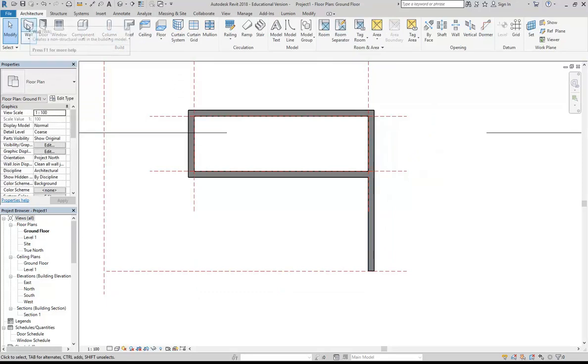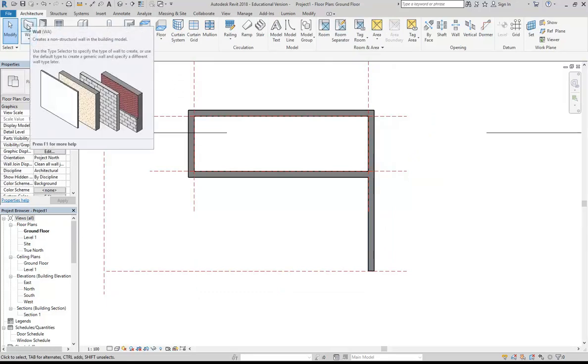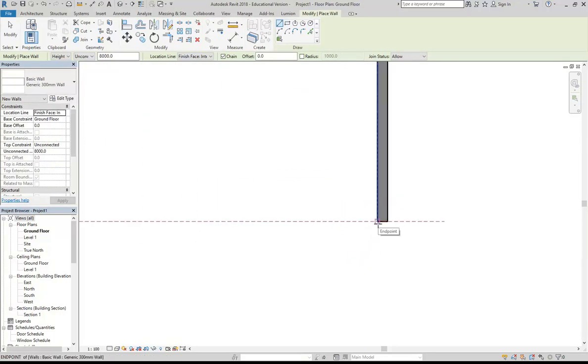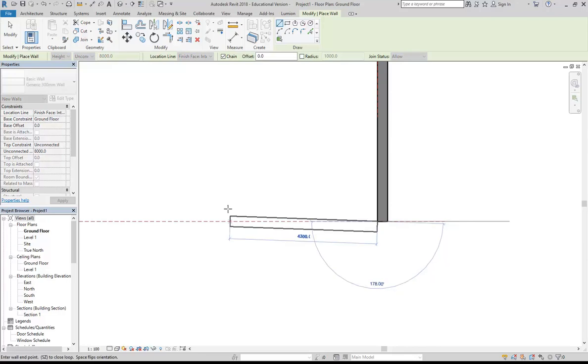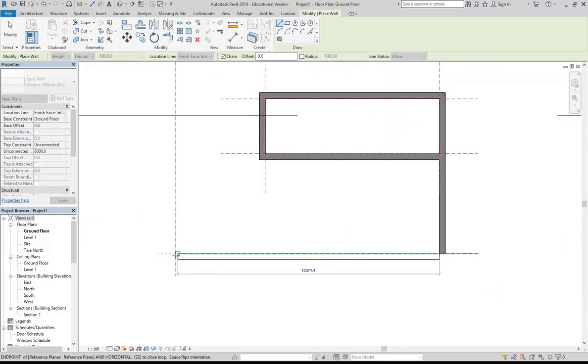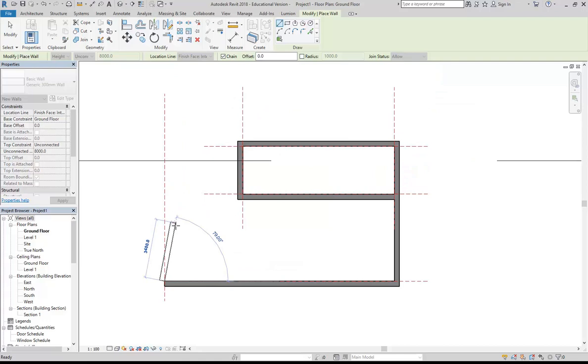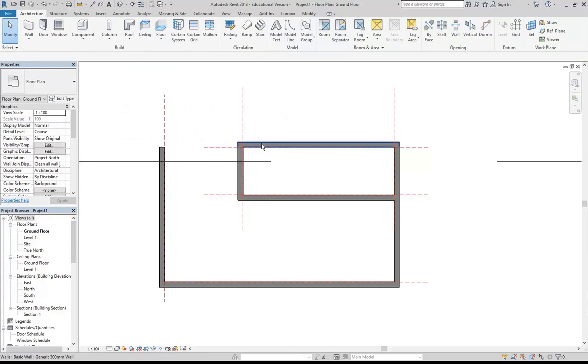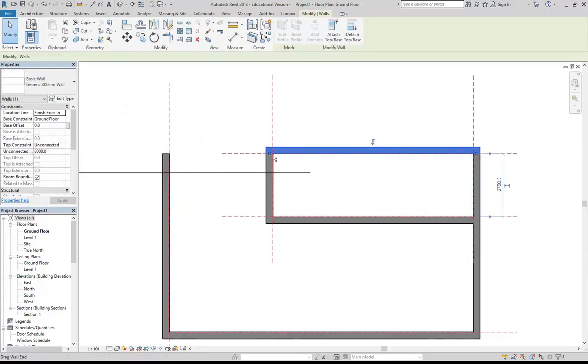Then I can continue drawing a new wall just using the wall tool again from this end of the wall I've just extended, going across to the left to my new reference plane, and then I'll bring it back up, and it'll even project. If you don't have that reference plane extended across, don't worry, it'll project across and work out where it intersects. But again here, I'm not going to take that across to the right now because it's better instead to extend this wall by stretching it.